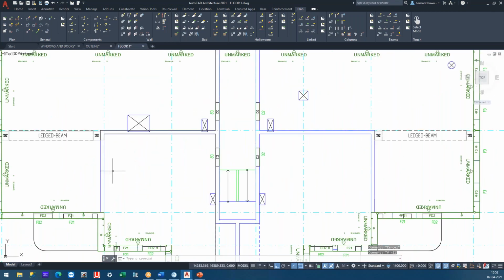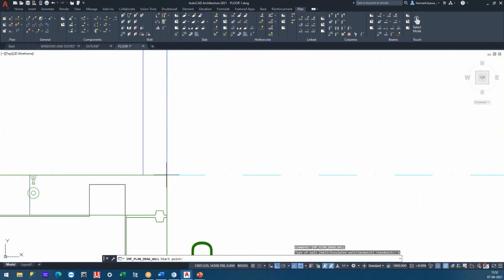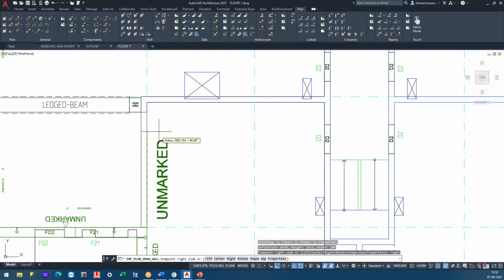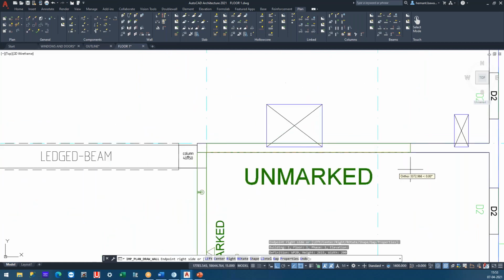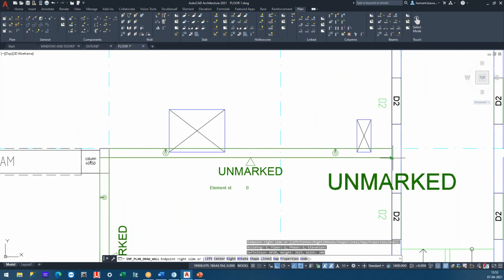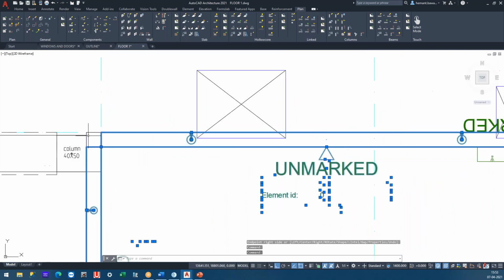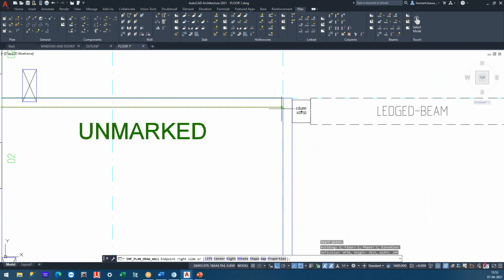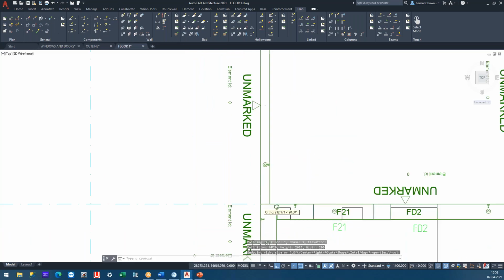As you can see, I have the solid walls to be drawn here. For this, we will just go normally. So I will select the wall extremes from here and adjust the orientation. Currently, as you can see, I left out this huge gap here, but that is okay for now because we will be connecting these walls and the software will adjust this length for us. Let me just draw on the other side as well. Done for this side.